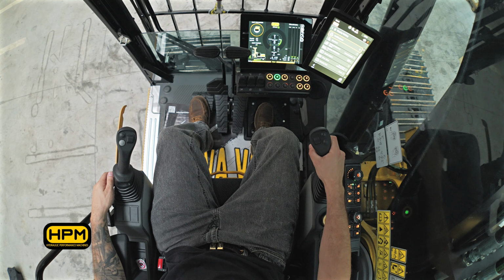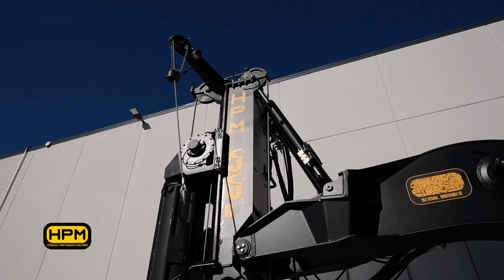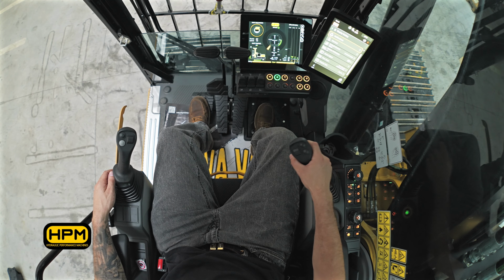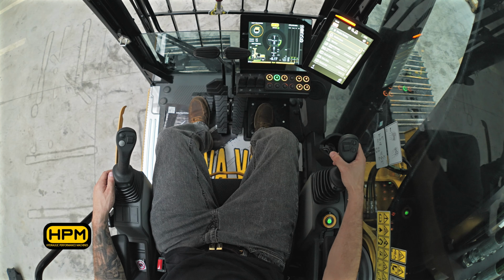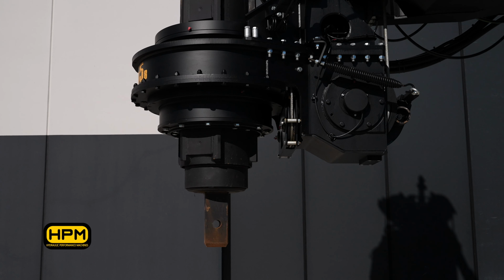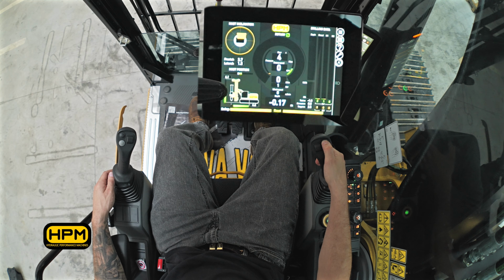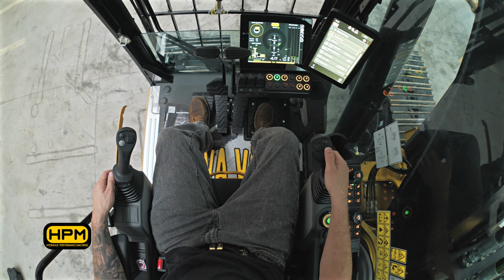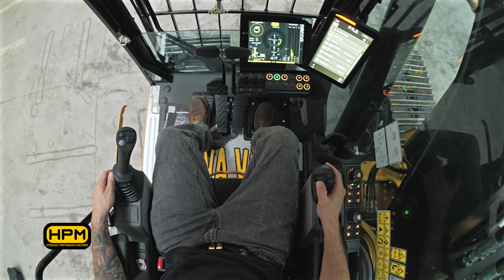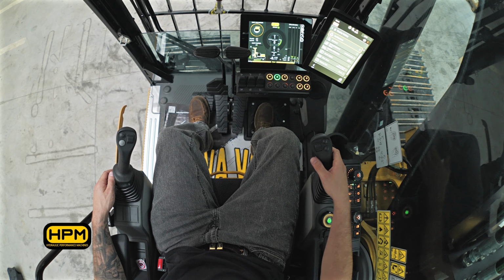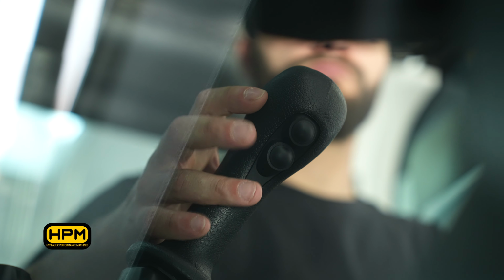Right joystick. Push down to crowd push. Pull up to crowd pull. Left, rotary clockwise. Right, rotary counterclockwise. Top button, gear up. Bottom button, gear down. Thumb wheel, pulling it together with the joystick, high-speed crowd pull on machines where available. Rear button, rotary spin-off gear. Override button.